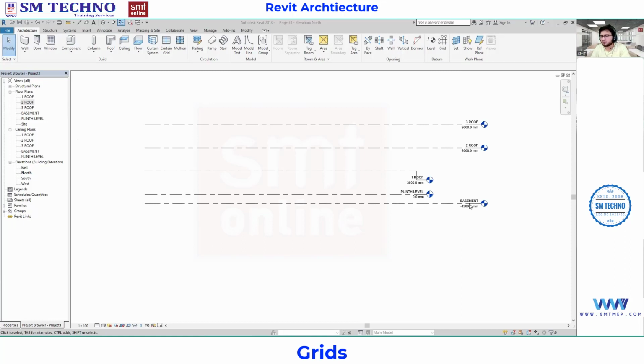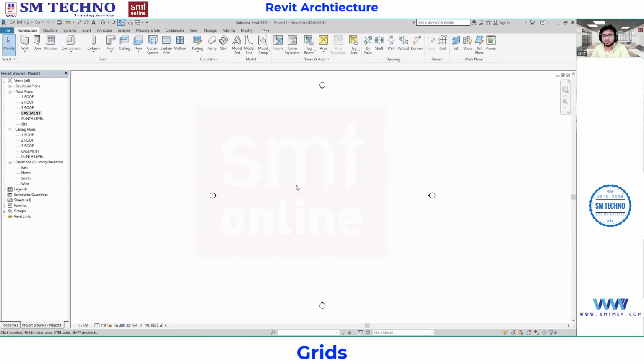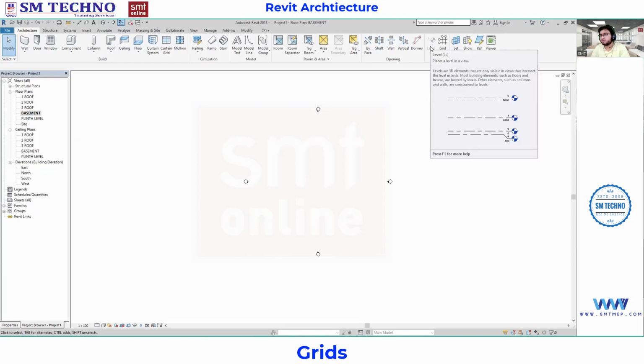I'll go with the bottom side, the basement. Go for the basement floor plan from here. Double click on this one. This is the limited basement floor plan. Now here we are going to sketch. In the same Architecture tab, in the Datum panel, can you see the level is hidden? Now it is disabled for us. This will be enabled only in the elevation view.